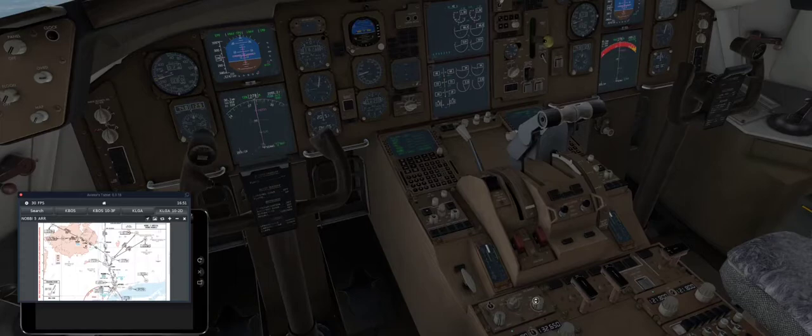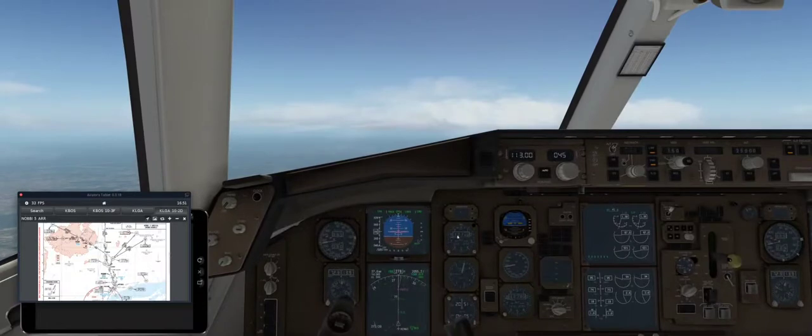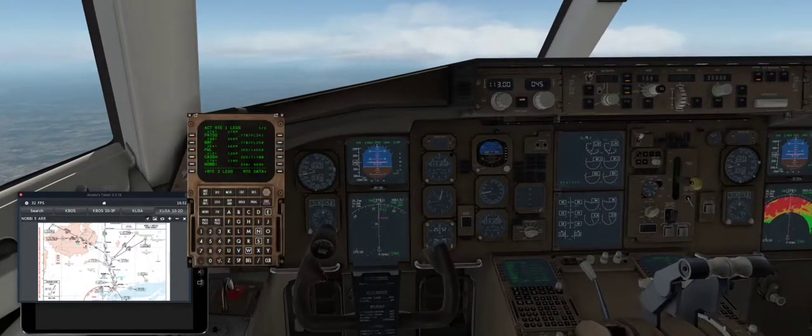Yeah, tilt that radar. I'm looking at the co-pilot's display. Tilt the radar until you've got the band as wide as it can possibly be. It's not going to fill the whole screen, because there's kind of like a cone from the nose of the aircraft where the radar can hit. That's probably where I'd leave it, right there. Almost at 18,000. That was our transition altitude.